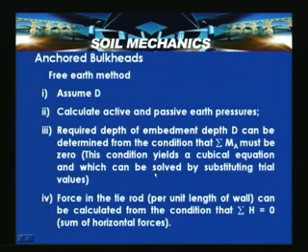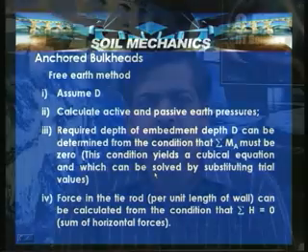So, this is the case where you have sandy soil on both sides. In this case you will get a cubical equation, but if this is a clay, then the pressure diagrams will be the same as what we discussed, like force E minus gamma H net pressure in front of the wall to the entire depth.